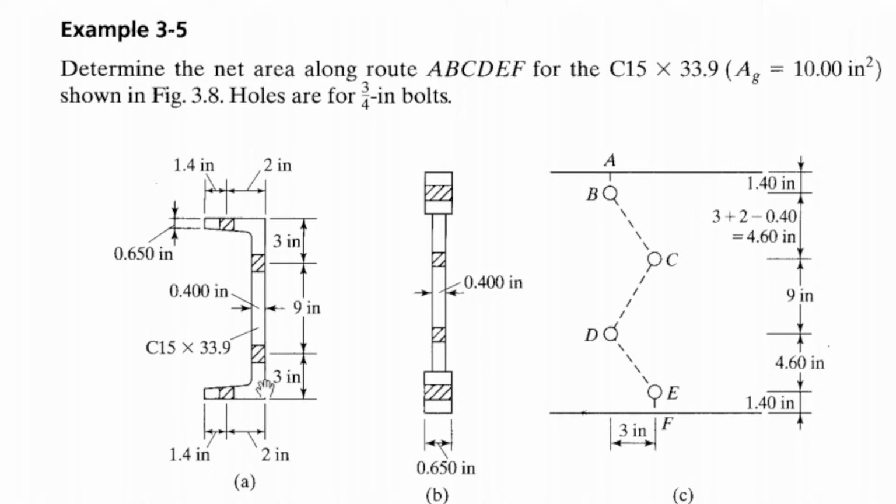If we are given W section, it is much simpler. Because usually in W section, there are times that the thickness of the web is equal to the thickness of the flange. And therefore, it is easier for W section to be represented by a straight plate. Straight steel plate like this. We want to model the C channel as the equivalent of this steel plate. Okay?